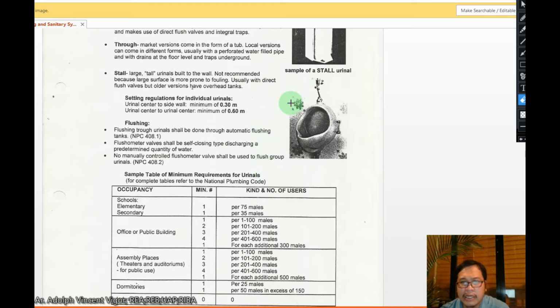Class, when you design your restrooms, you should be wary in placing windows. No, not windows, mirrors. In placing mirrors, because sometimes I've noticed that designers, if the urinals are located here in an array with divisions, place it directly facing a mirror, so there's no privacy.